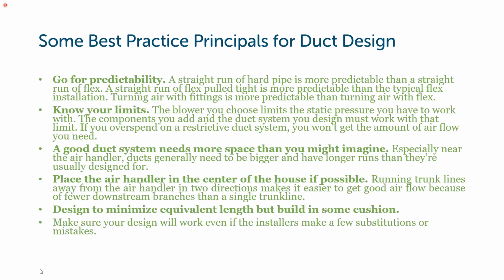So, making sure, as again, we're talking about this as a design document, if you can look at the plan set with the HVAC contractor and have a conversation as to where they're going to put their ductwork in the drawings, then they don't have any surprises when they show up to the site to do their rough-in and there's a Parallam beam running down the middle of where they want to run their trunk line, or there's a header that they can't go through to run supplies to one section of the house where they thought they could before.